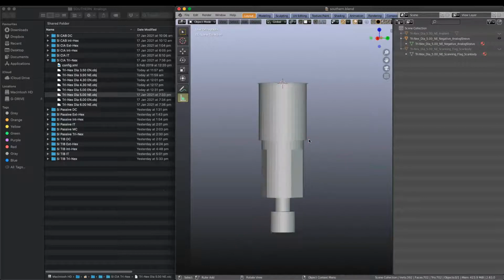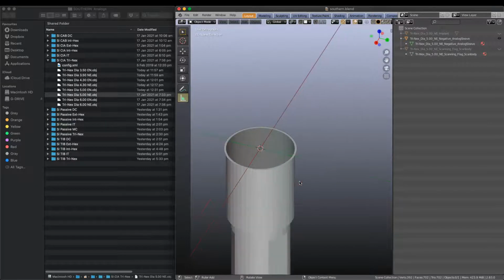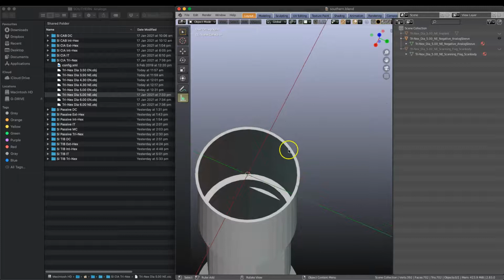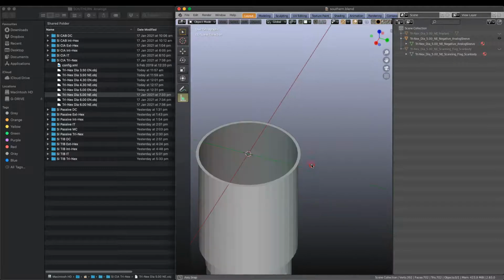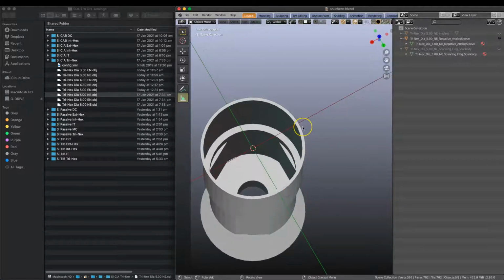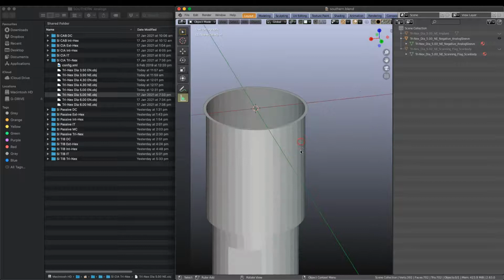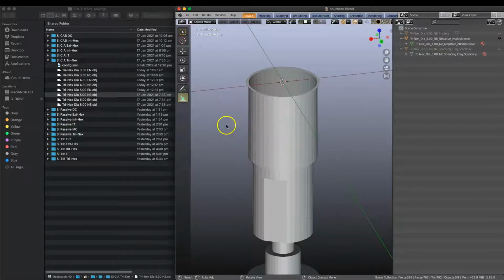If we have a look at this part, we can see that the bottom end caters for a screw, and this screw will tighten the analog from underneath the dental model. So already they have incorporated a ledge on the edge of this part. Now with these components I like to keep a wall thickness of 0.7 millimeters. That is to make sure it will print out, and in case you want to use the Gum Designer module